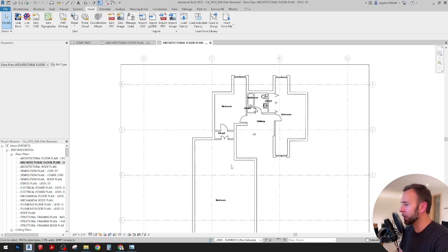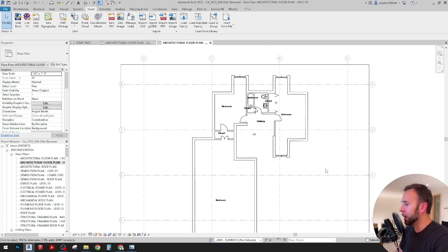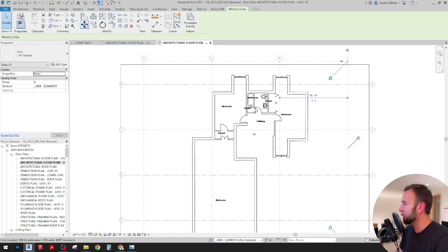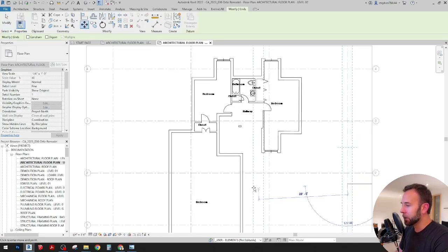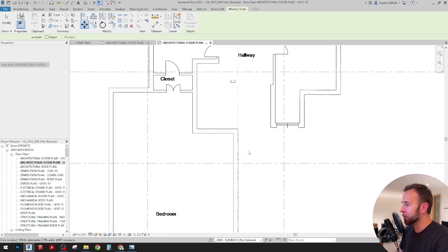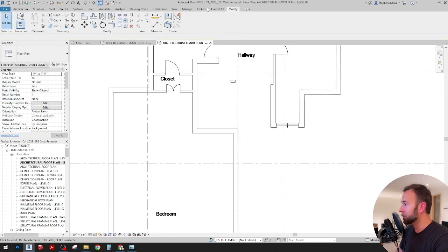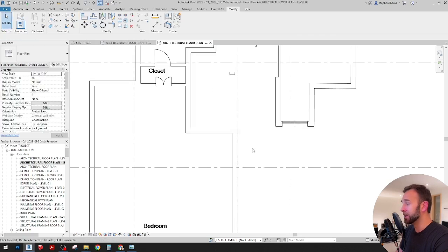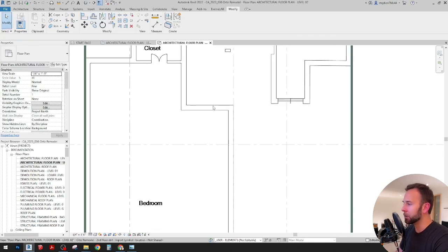So the first thing I like to do is align my grids. So I'm just going to take this and drag it over. The reason I don't use the align tool, which is right here, for that process is sometimes, even though you select the straighten off-axis lines when you're importing, the lines can still be non-orthogonal.